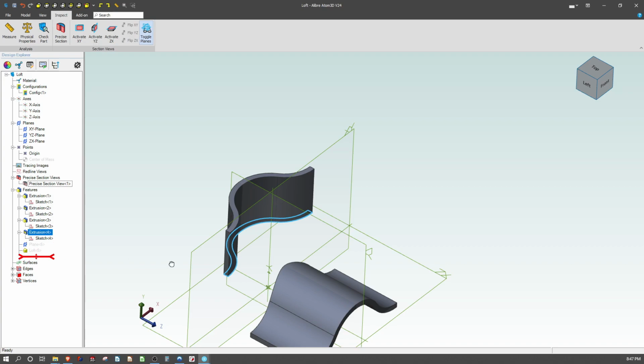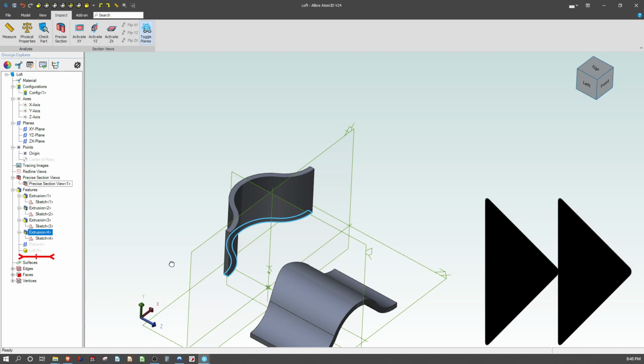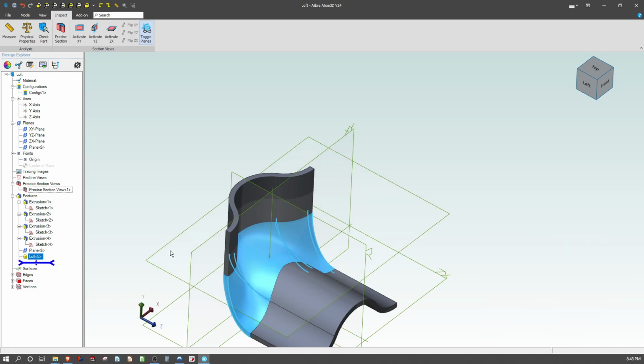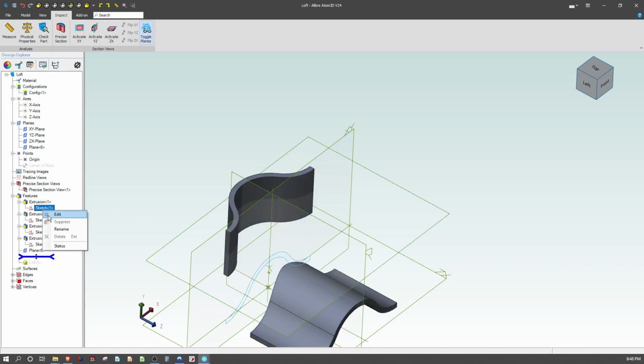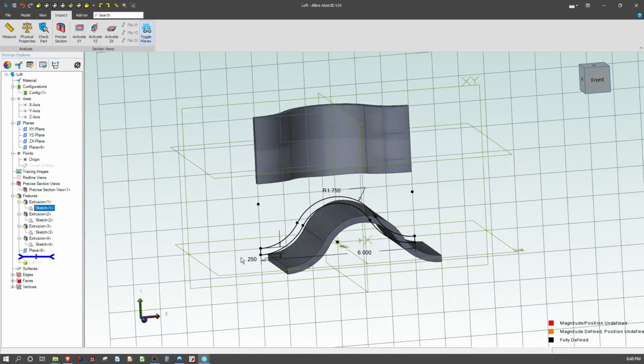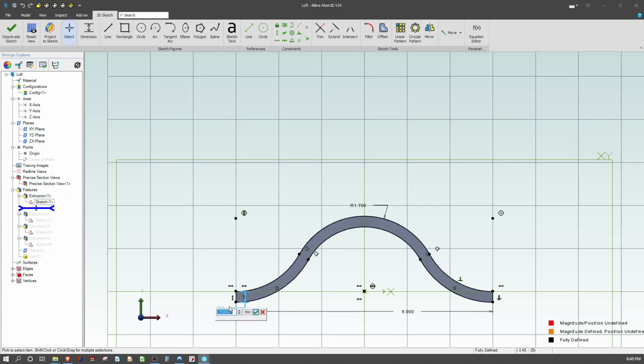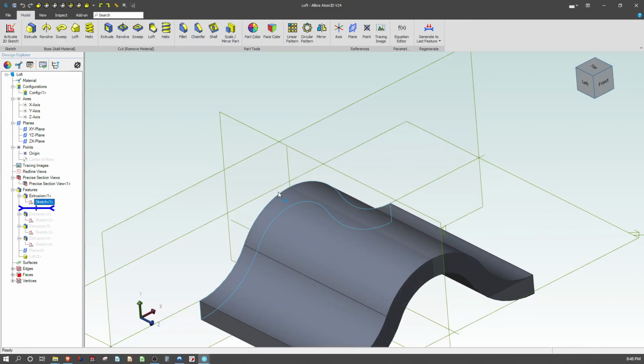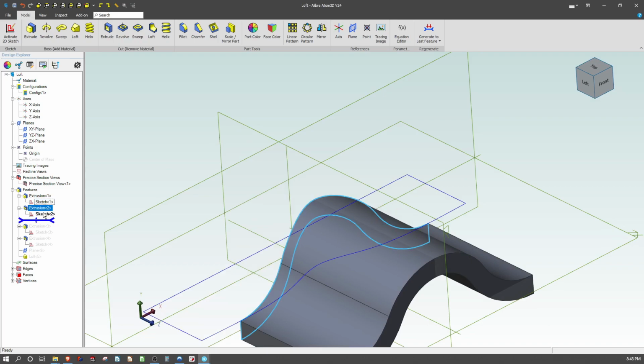This takes a second to think here. Okay, so let's modify this, right? I'm going to roll back before the loft, and that will help speed up our rebuild times. But let's go to the original sketch. And we're going to make this more thick than we want. I'm going to bring it up to, say, 0.5. And we can see we have a much thicker loft.